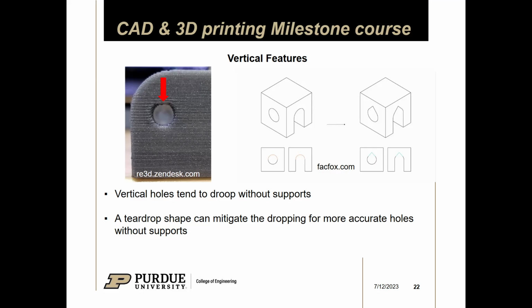Another example of overhangs is holes. You may not have thought about this originally, at least I didn't, but if you think about a hole, the angle at which you'd have to print the top of it becomes progressively higher and higher, right? If you drew a line tangent to the circle and dragged it up to the top of the circle, it's completely flat, right?